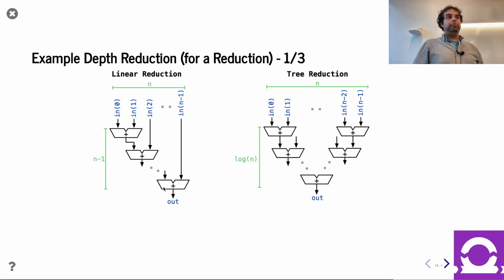Because of the language semantics, Chisel and Verilog specify what the width of a non-truncating addition is. Well, it's the maximum input width plus 1. Because of that constraint, this design is going to have over-provisioned bits.